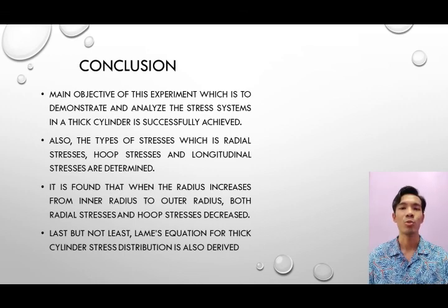Other than that, it is found that when the radius increases, from the inner radius to the outer radius, both radial stresses and hoop stresses decrease. And last but not least, Lamé's equation for thick cylinder stress distribution theory was successfully derived.